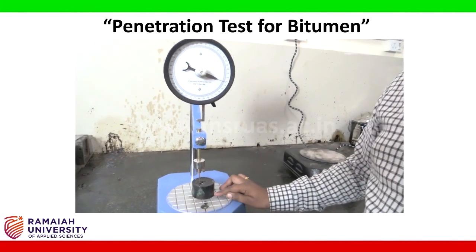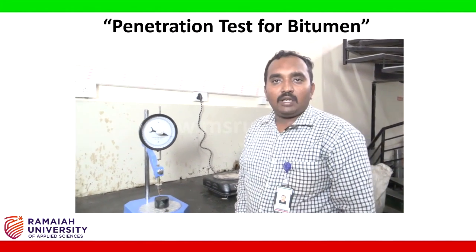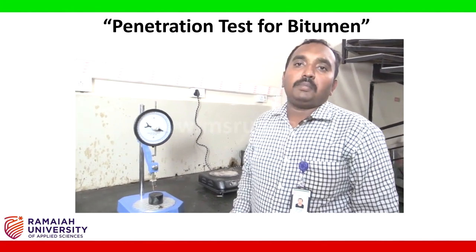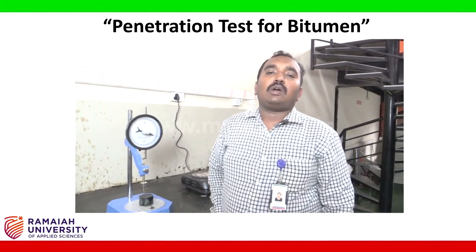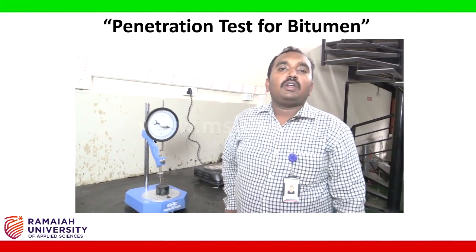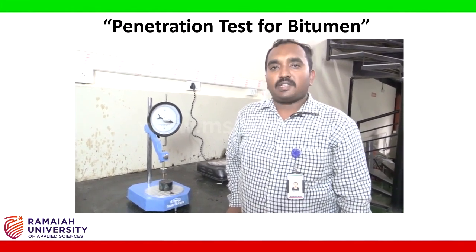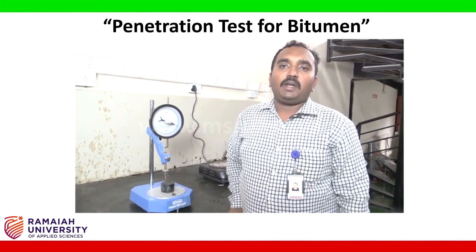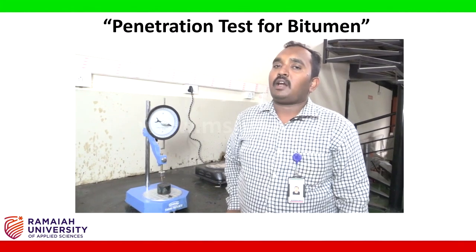The average depth of penetration gives you the penetration of the bitumen and it gives you the grades of the bitumen. If your penetration value is between 30 to 40, it's called 30/40 grade bitumen. If it is between 60 to 70, it's called 60/70 grade bitumen. And if it is somewhere between 80 to 100, we call it 80/100 grade bitumen.